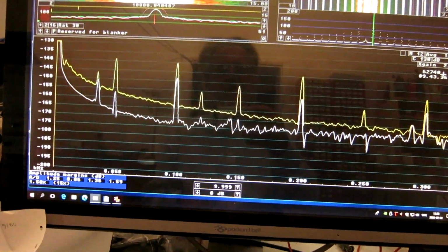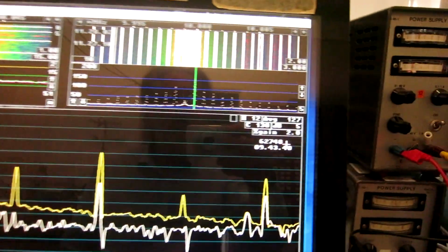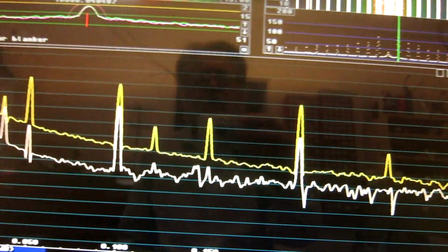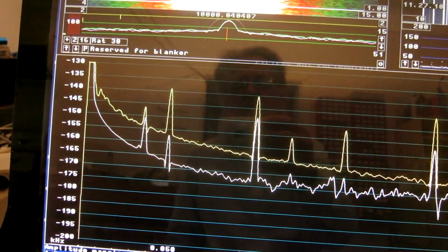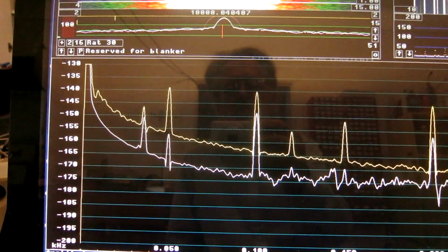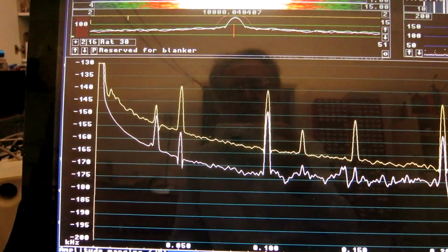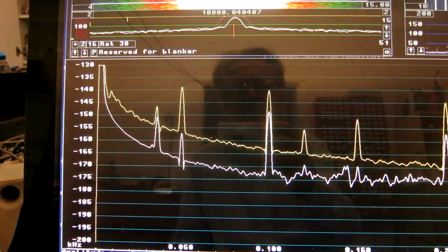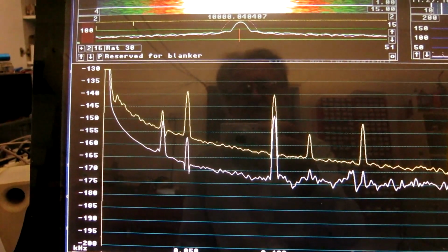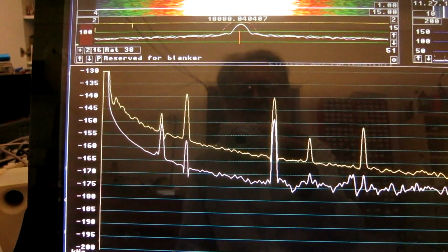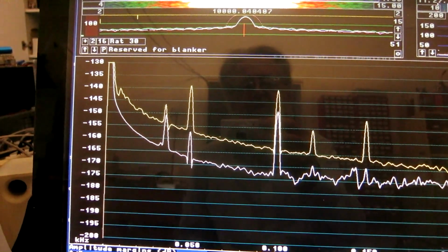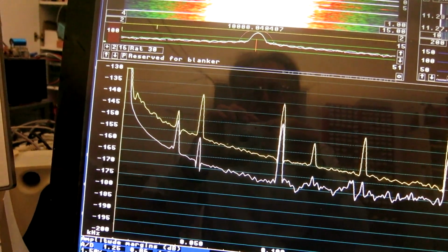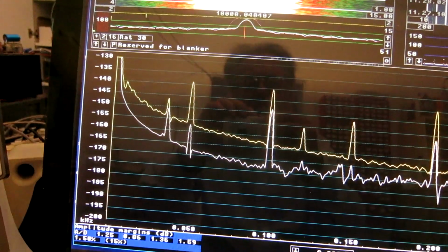Here is the signal analyzer output after 9 hours and 45 minutes. The amplitude noise is now much lower than before. The clipper is operating properly and it attenuates the level by about 8 decibels. So it's a much harder clipping than before, and it is giving a nicely looking square wave. I will save these results to get from paper what the levels are.